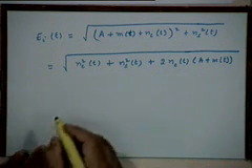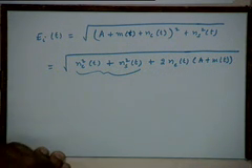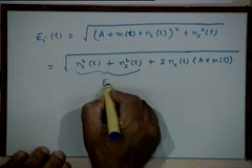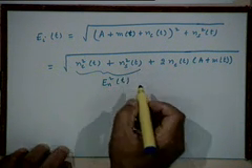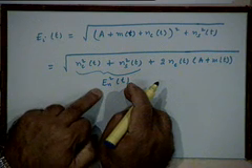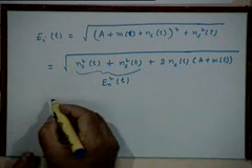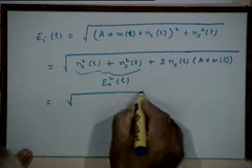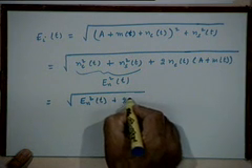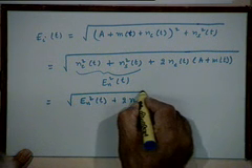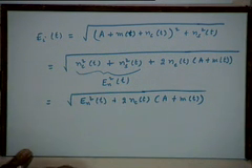Okay. Now, denoting by E_n square t the quantity n_c square t plus n_s square t, which gives you the instantaneous envelope of the noise alone, right, then we can write this as the square root of E_n square t plus 2 n_c(t) into A plus m(t), right.